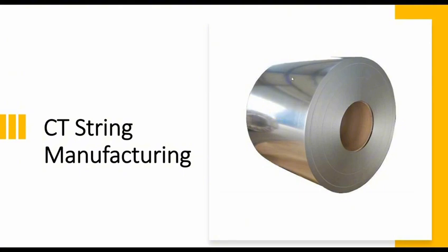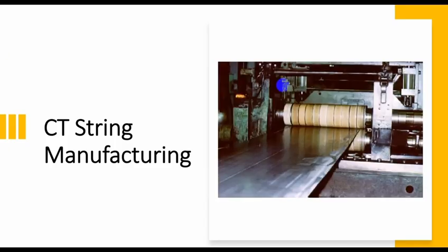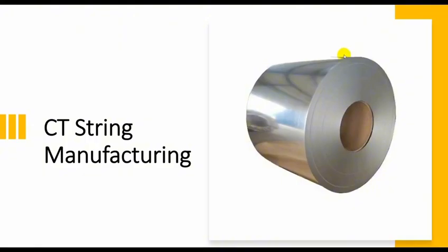So this came to the factory as a raw material. Then we slit the 55-inch width to much smaller widths. These widths make the circumference of the coil tube, and determine the OD, or outer diameter, of the coil tube pipe. The thickness of this sheet will determine the wall thickness of the coil tube.